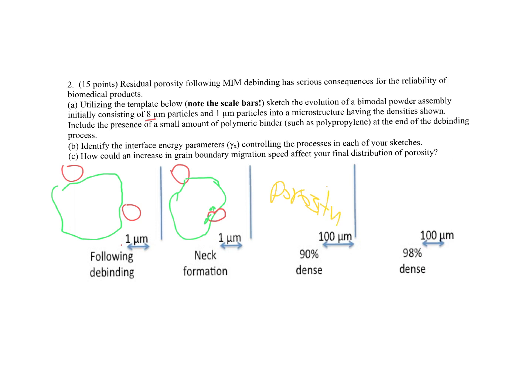Where is it likely to be? Notice again, I've jumped up to 100 microns. So you can give me a lot of information on this. You might assume some grain growth. All those kinds of things could happen. And then at 98%, where's the porosity there as we transit from stage 2 to stage 3 of sintering? Does that make sense? Hopefully it doesn't seem too daunting to draw microstructures like this. Right, again, the whole sketching thing really helps hammer home the intuitiveness of this. All right. Any questions about that?